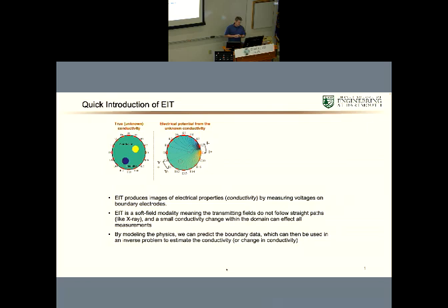Unfortunately, EIT is a soft field modality, so it's not like X-ray where you shoot the X-rays right through stuff. In EIT, the current diffuses easily through the domain, and a small conductivity change in some part of the domain will affect all the measurements. So it's a tough inverse problem, but we model the physics.